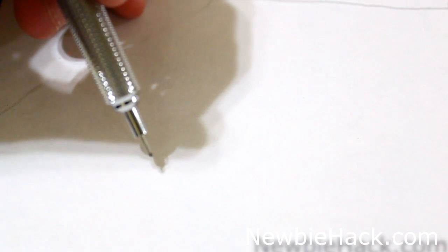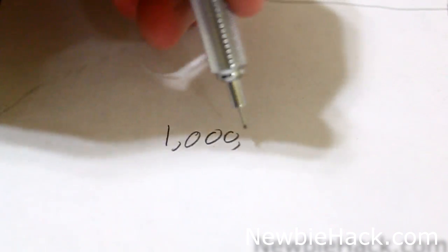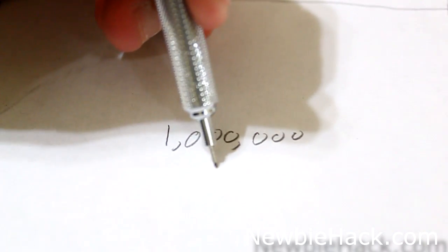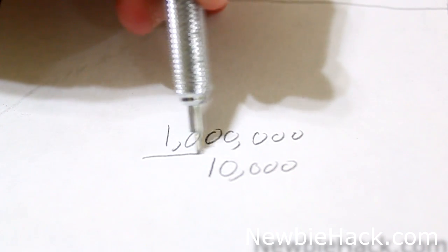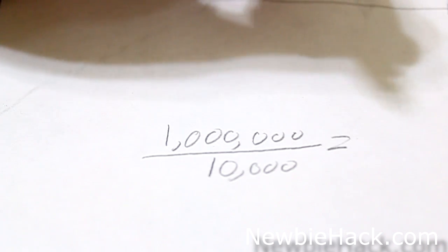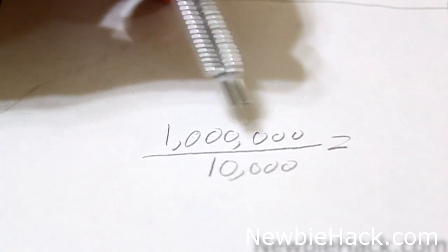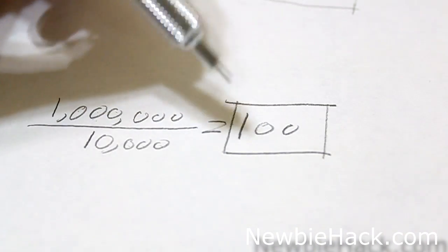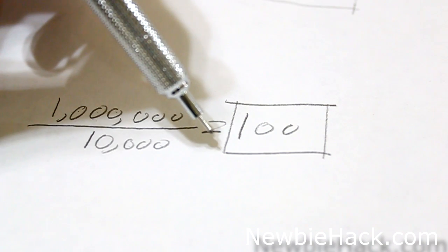So what we've just done is we took a number that is 1 million, which is the internal clock, and every 10,000 times it's going to blink. So let's see how many times per second that is. That's 1, 2, 3, 4, 1, 2, 3, 4, 5, 6, so that's 2 zeros left over. So the LED is actually blinking 100 times per second,